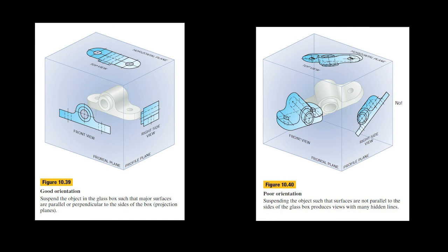A hole generally partially or completely passes through the object, so you cannot really depict the entire depth or length of the hole using the thick outlines, because that feature of the hole is interior to the object. So then you use hidden lines to depict the limiting elements of the hole.